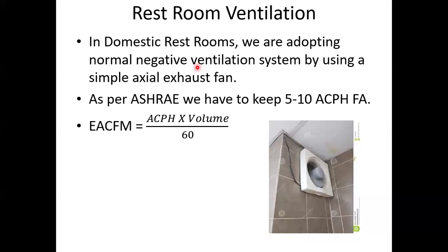So area into height. That's it. We got the value. And after that, here is the main concept. It's about the ACPH. So how to calculate the ACPH? The ACPH value lies in between, for domestic restrooms, around 5 to 10. Okay, what is the value, guys?